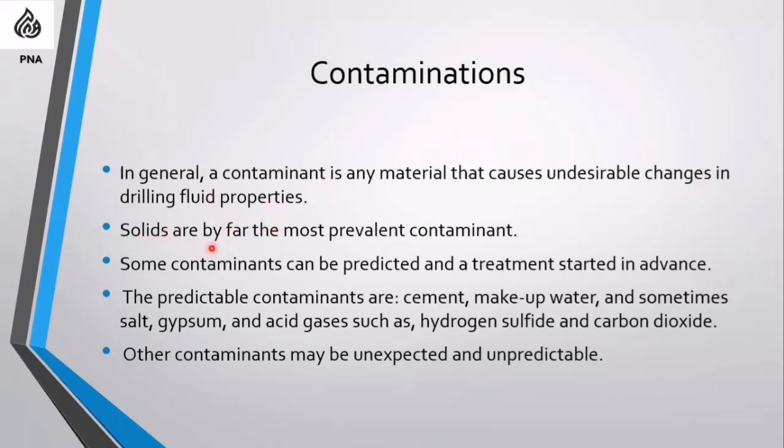Solids are by far the most prevalent contaminant. The first enemy for the mud engineer is the solids, or drill solids. Some contaminants can be predicted and treatment started in advance. These predictable contaminants are cement or makeup water, and sometimes salt or gypsum, and acid gases such as H2S or CO2.